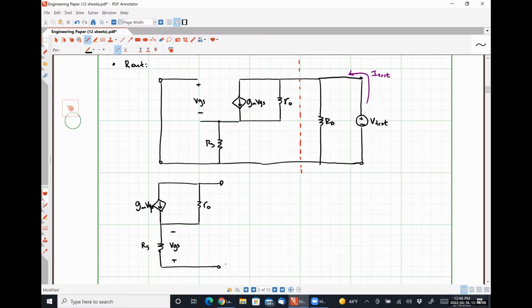All right. So if I want the equivalent resistance network, I need to apply a test source method, right? Because it has a dependent source in it. So if I apply a test voltage, which in this case I'm going to call Vx, so it's not confusing since I already have a test source applied to my top network, I am now trying to determine this quantity Ix. And the ratio of Vx to Ix will be the equivalent resistance of everything to the left of the dashed line. Are we okay with that? All right, so